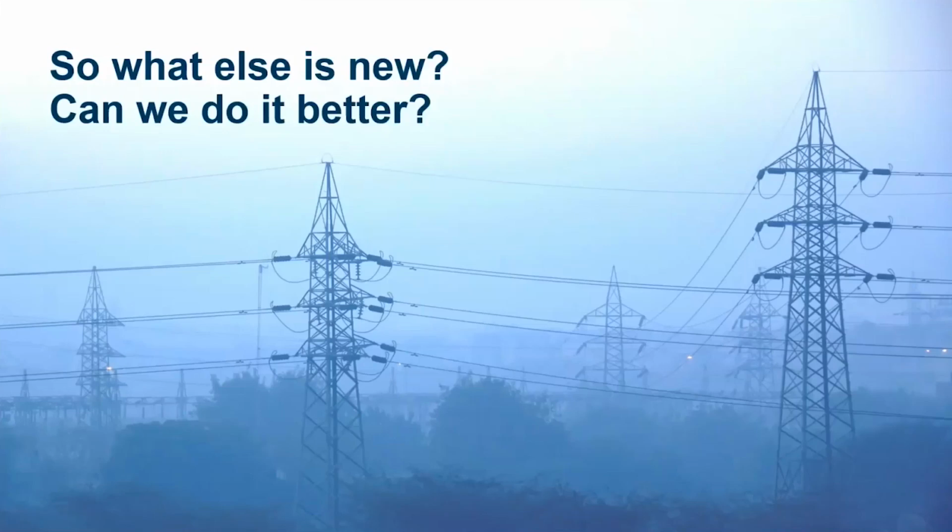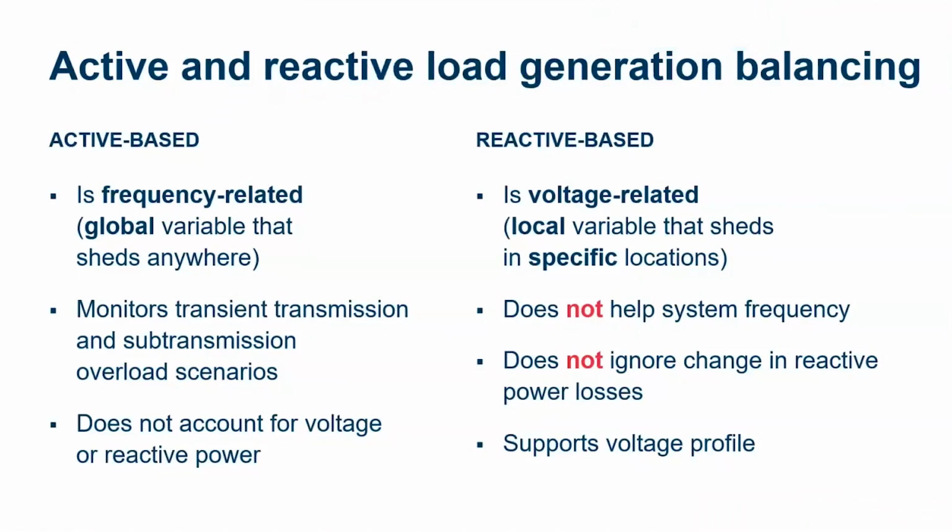Now that we've looked at the basics of a typical RAS system and control action, let's dig a little bit deeper on what can we do better. How can we innovate? Currently, we offer active power-based load shedding where we can enhance our control scheme by utilizing reactive power as well, so that we can offer a reactive power-based load generation balancing. We looked at high-speed load generation rebalancing to keep the frequency inside the regulation limit, but these actions may not account for voltage or reactive power imbalance as they focus primarily on power and frequency.